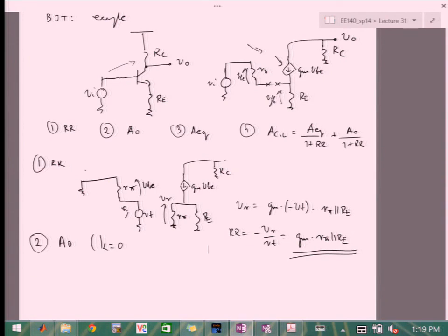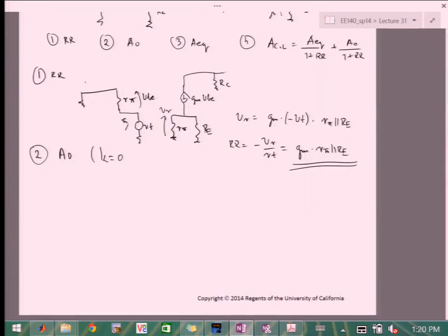K was this parameter that was kind of like if there was an amplifier with V error, then the output was K V error, right? Or in that case, K was just A, right? But in the single transistor case, what is K? GM, that's right. So in this case, that means that GM equals 0.